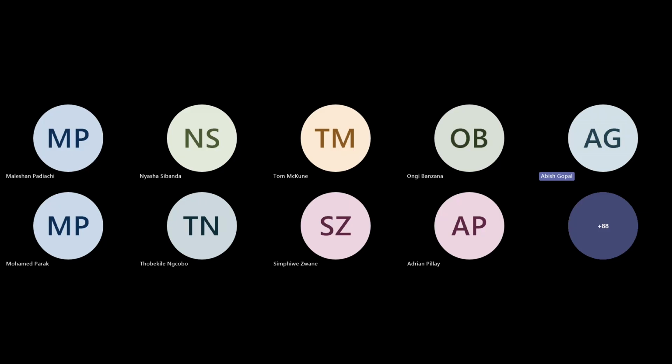From that location onwards, because of the concentrated forces, as the entire deck rotated, it was concentrated towards the edge of the pier. That's where there's a point load acting upon the deck. Hence, the diaphragm transverse beam surpassed its initial design shear capacity, and that was what led to those shear cracks. But in terms of the main girders, no.